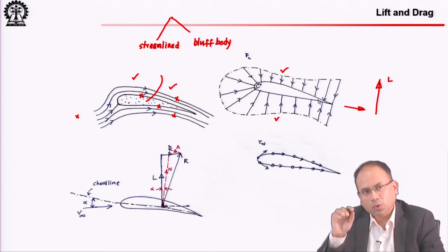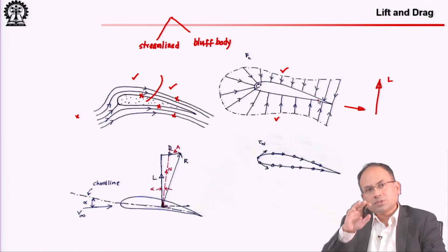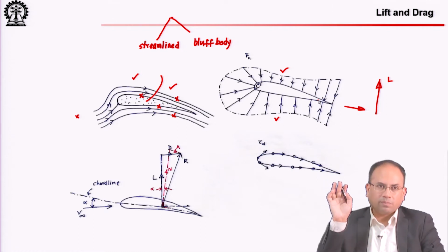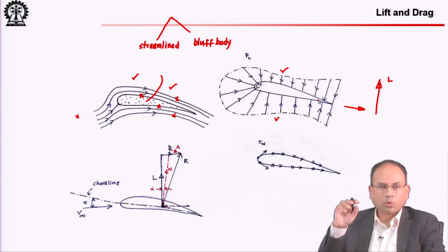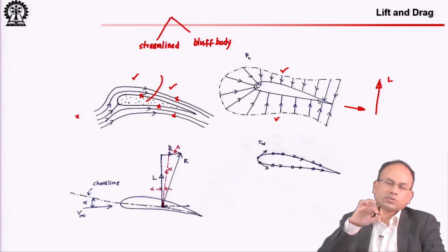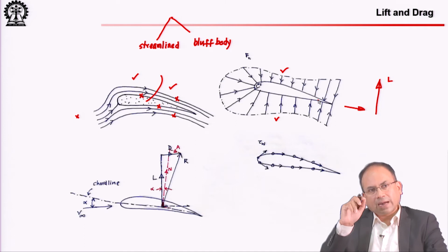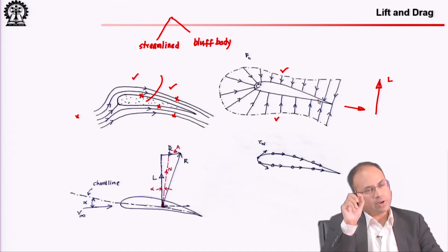So, that is why the normal forces are still important in the discussion of drag, because when flow separates over the surface of the wing or whatever body you are talking about, that is when some imbalance of the normal force in the direction of the relative wind happens, and that contributes to a large amount of drag.